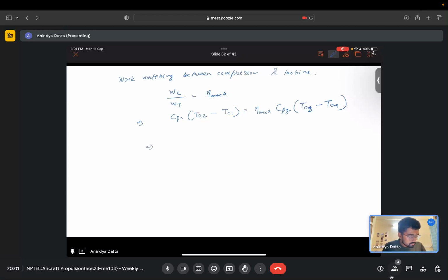So this is 1005 times T02, which is 496.09, minus T01, 251.76, equals 0.99 times 1157 times T03, which is 1350, minus T04.